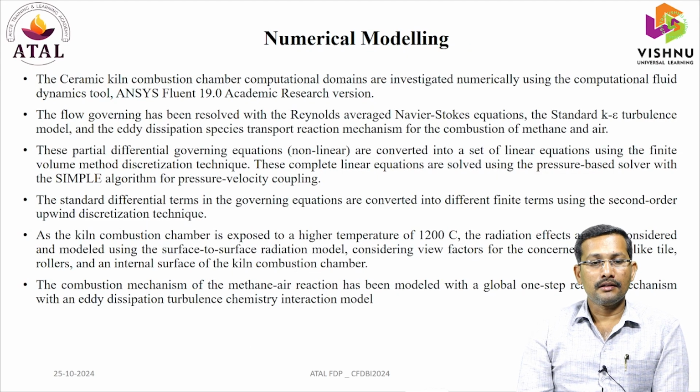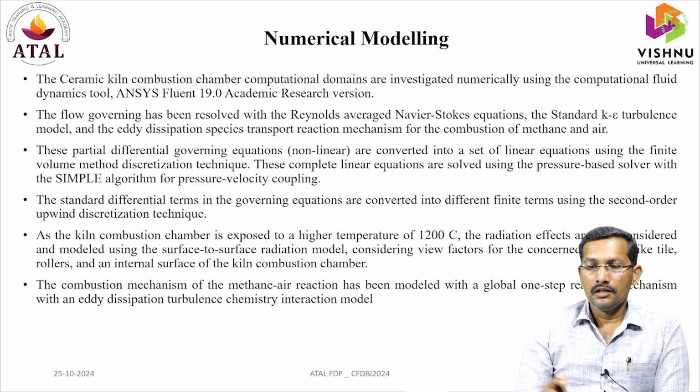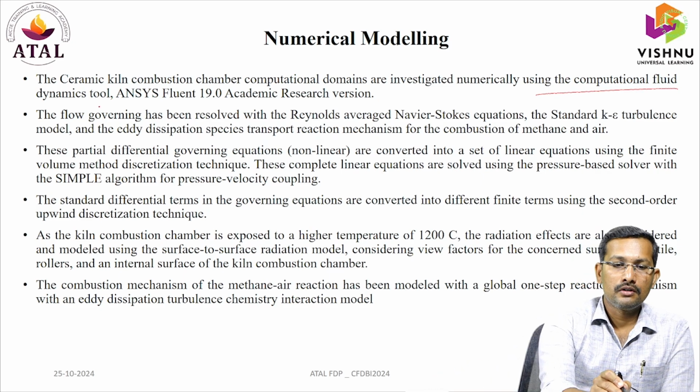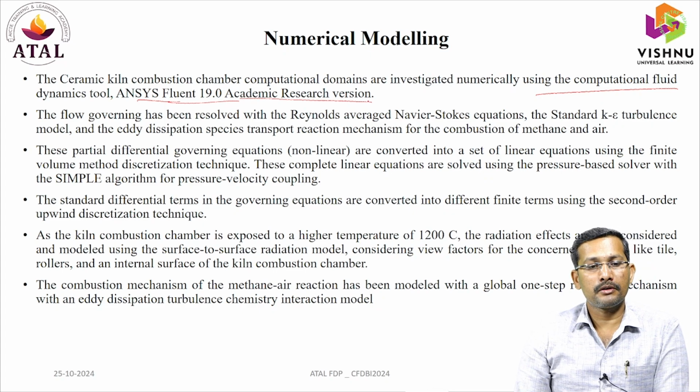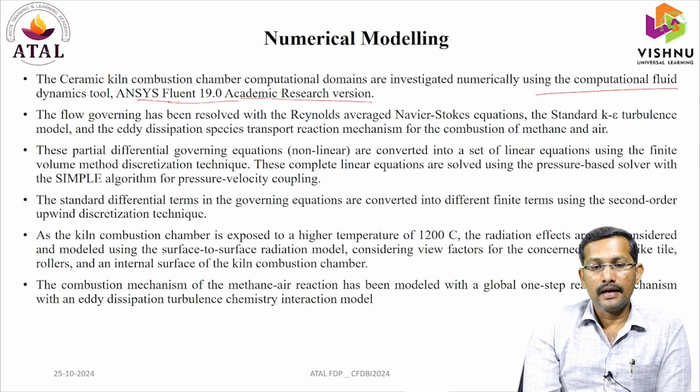In the numerical modeling, the ceramic kiln combustion chamber computational domain is investigated numerically using the computational fluid dynamics tool, ANSYS Fluent 19.1 academic research version. It is available in our department. The flow is governed by the Reynolds-averaged Navier-Stokes equations.